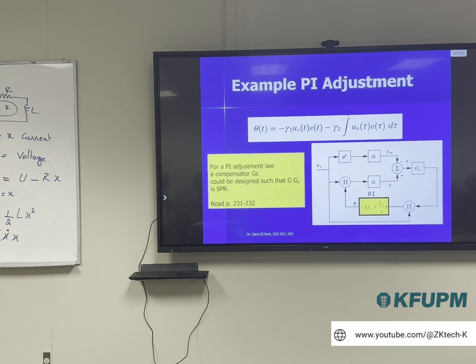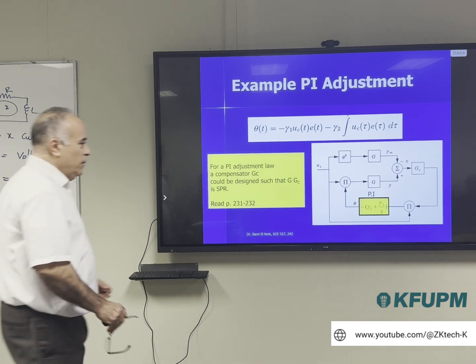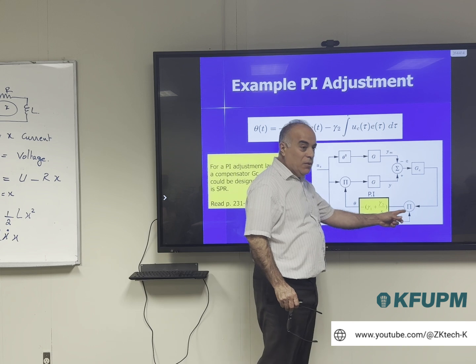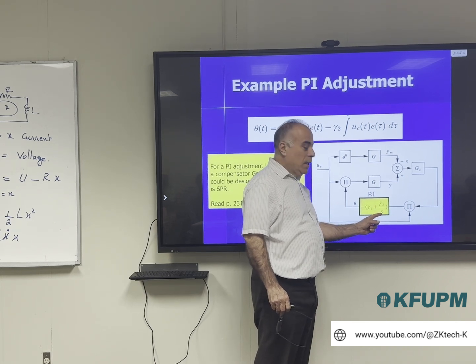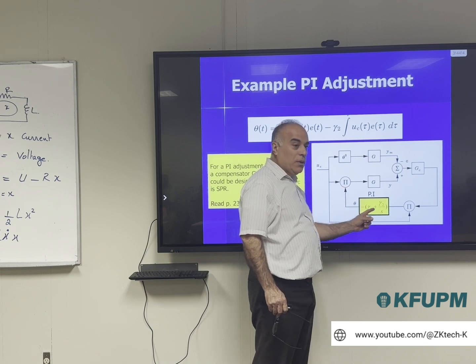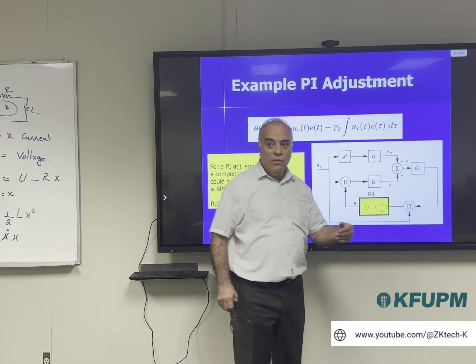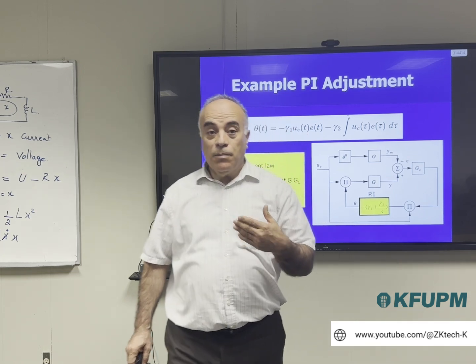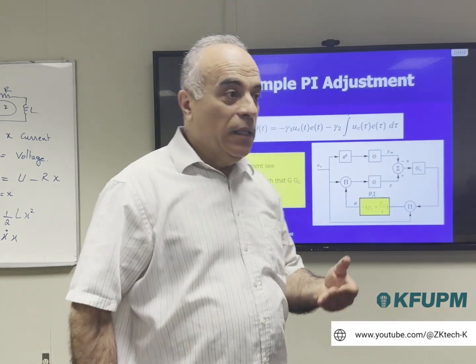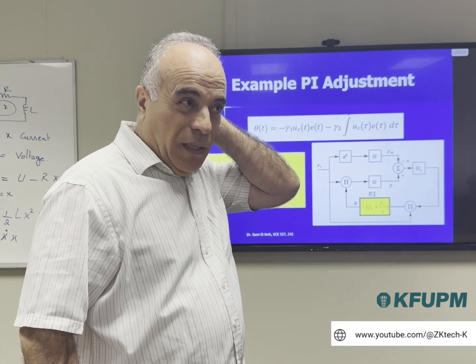So proportional integral. If I put it at a proportional integral, I will be able to control the speed at which I'm going to make the adaptation. And I'm also going to make sure that theta tries to converge to theta 0 as we go on. So here it allows me to explore different adaptation algorithms. Is it clear what I said here?